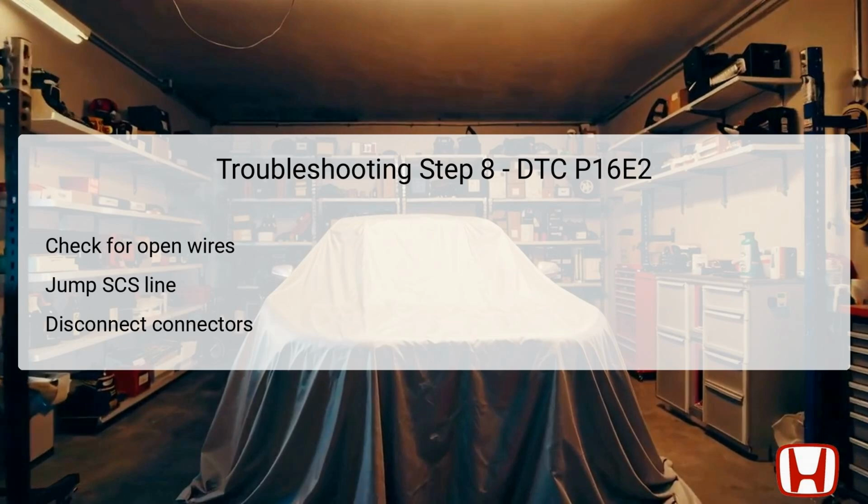Test point 1 will reference the alternator's female terminal number 1, and test point 2 will connect to PCM connector A's number 10 terminal. A reading of 1 ohm or less indicates that the LIN wire is functioning as intended. A higher measurement means an open circuit needs repair.